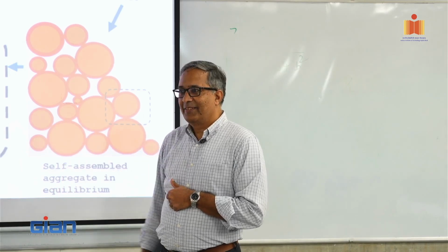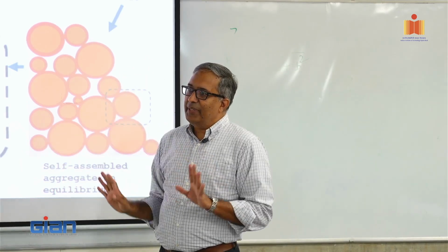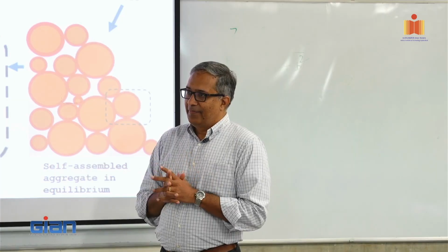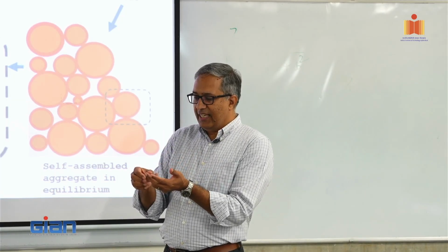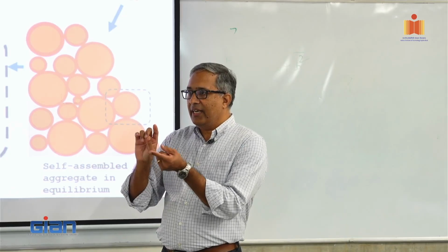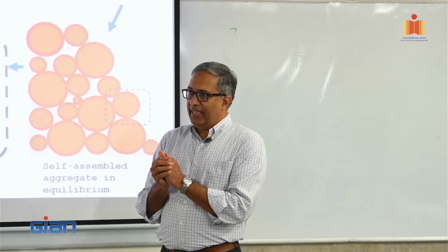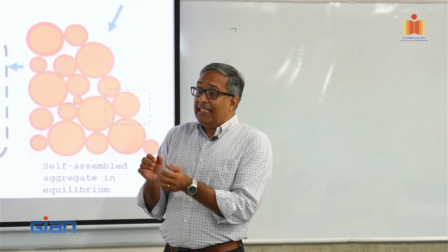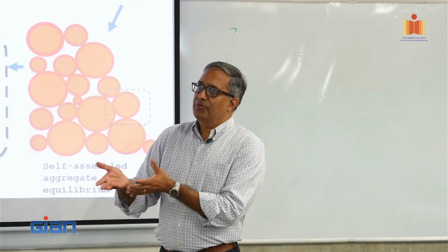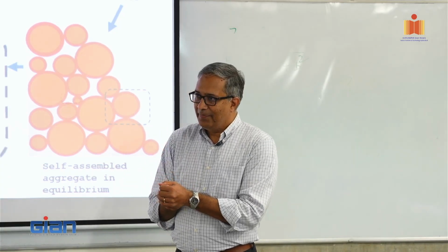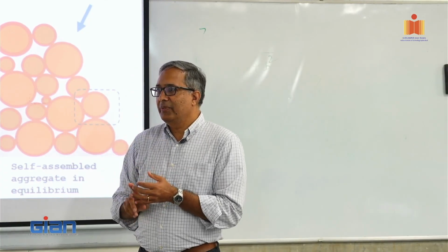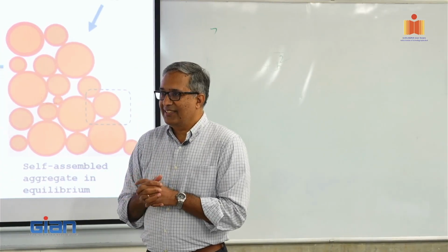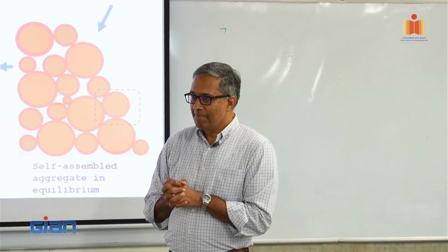All three boxes have to be ticked. I have only so many levers in my hand. I can control the water content, the cement content, the aggregate content, and the breakup between coarse and fine. And if all else fails, I bring in some admixture to help me a little bit. But you cannot compromise on strength or durability. Those are the hardened properties.